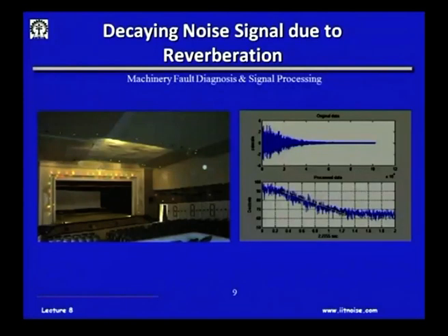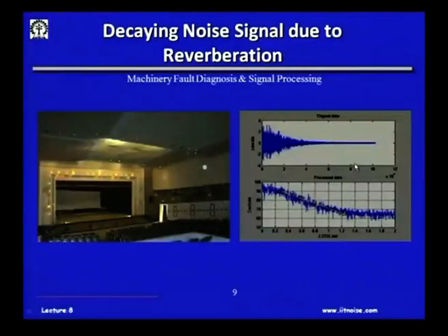So, reverberation time is estimated by this method, and this is how a typical signal looks like. You see the decay, and the time taken for the noise level to come down by 60 decibels is what is known as the reverberation time. Some of the opera houses have typical values of 2 seconds, like the Sydney Opera House. If you clap, you can hear it ringing inside for about 2 seconds. But we cannot afford to have that in a classroom or a conference room, it has to be much less. So, you would characterize this as a non-stationary signal, because this is happening once, it is not repeating, it is not stationary.